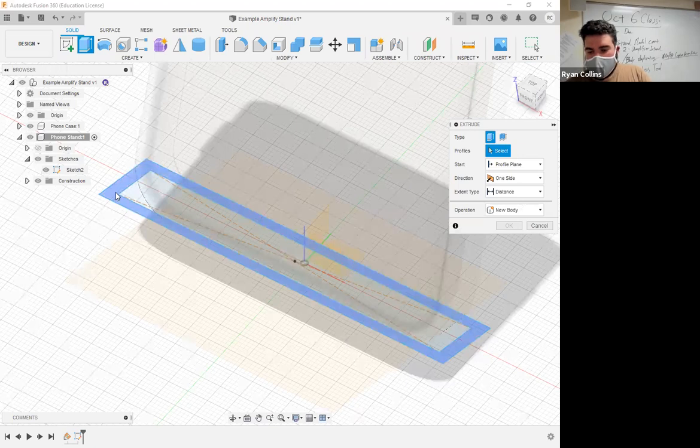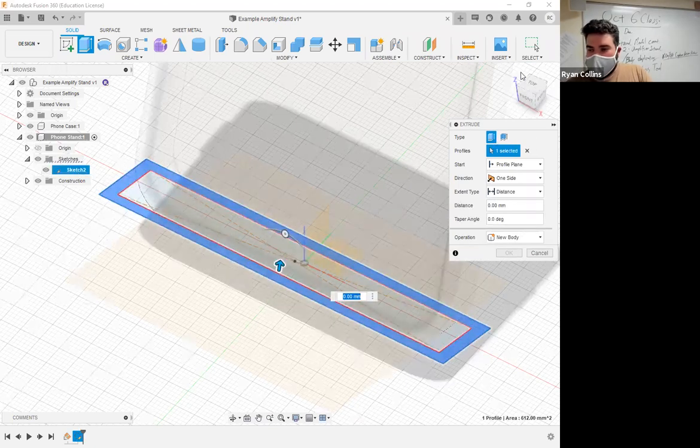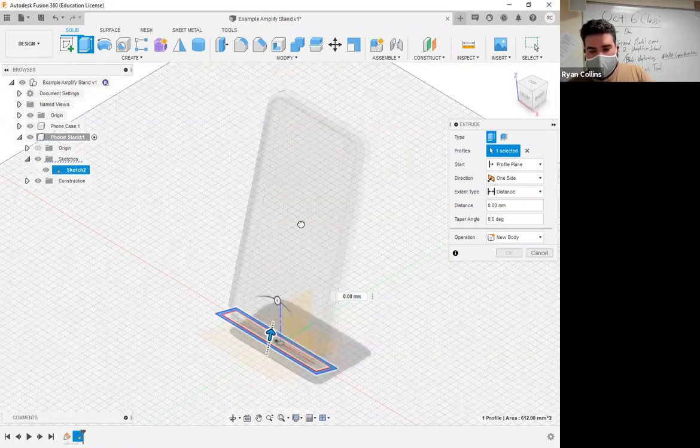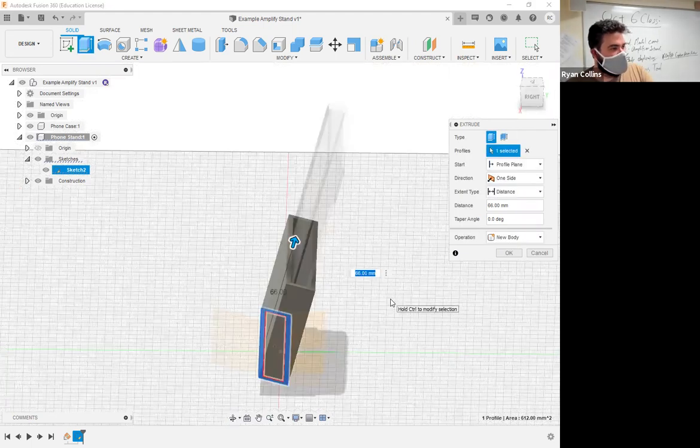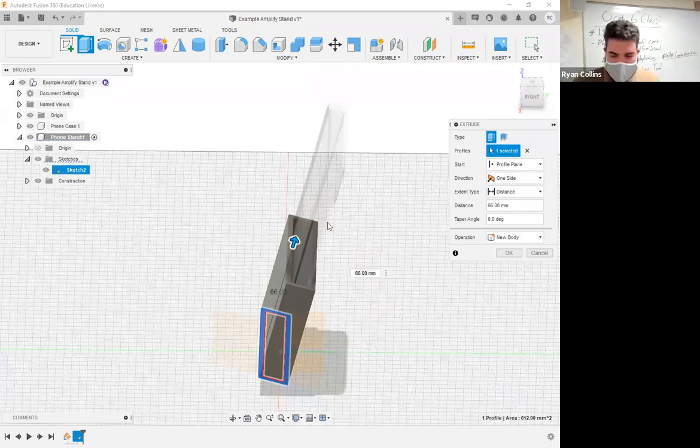And I just want the wall here. And remember that this is not extruding just straight up. It's extruding along that diagonal. So that's why I wanted to go ahead and build this all on the construction plane instead of on the existing plane, because it just eliminates having to finagle things back and forth. All right, so let's see here. I want this to go up enough to where it'll hold the phone easily, but without it being just ridiculous. So 75 millimeters seems about right. Go 75.